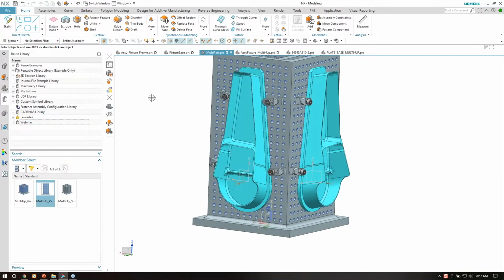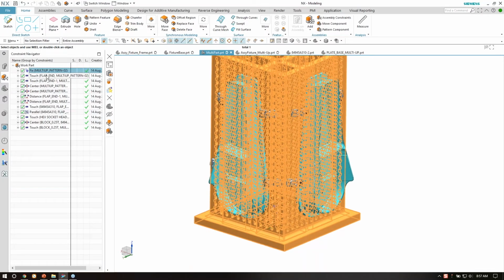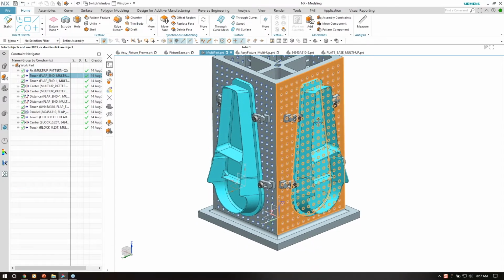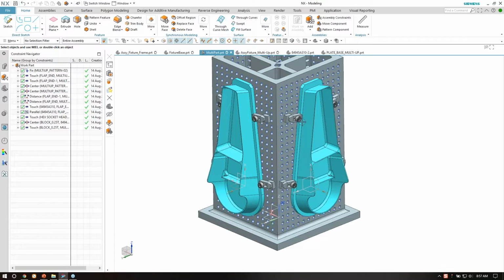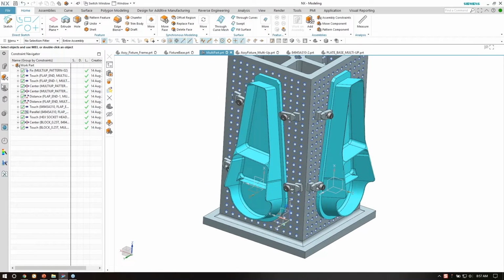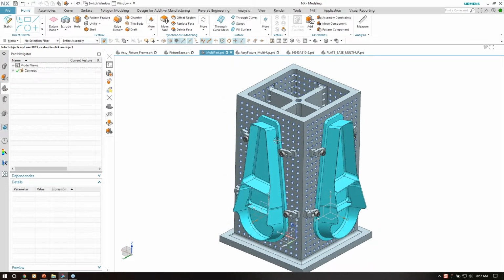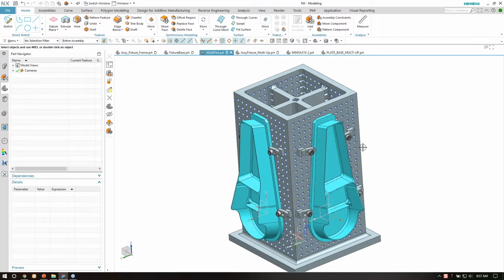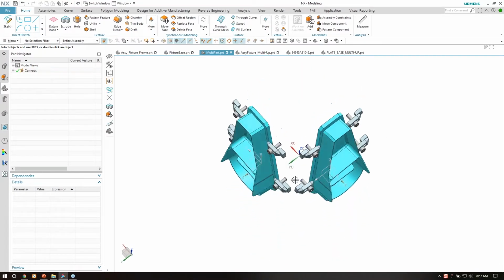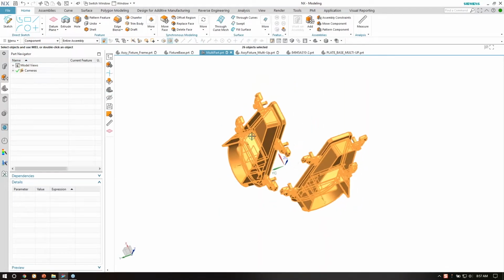This one, I've minimized how many assembly constraints I have in it. In fact, I've just got a few things in here as far as fixed. I've got a few things that are touching and centering up my part on my tombstone here. But again, if I wanted to fully populate this tombstone, this is basically a right and a left of this particular part. I'm going to hide all these components, and I want to switch my filter to component and select them all.